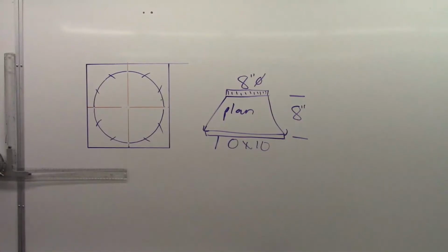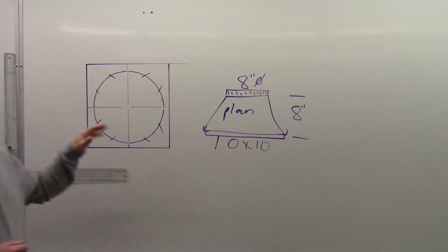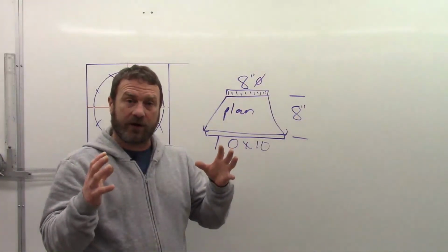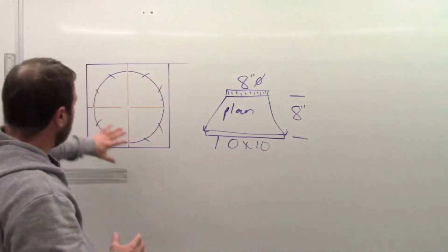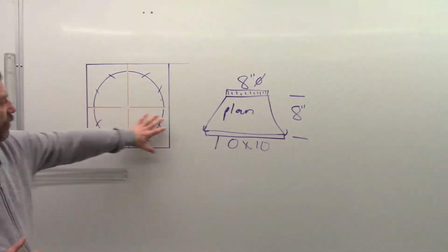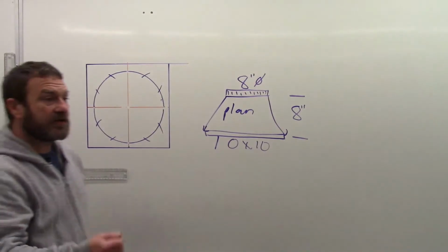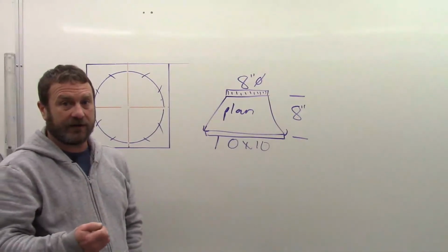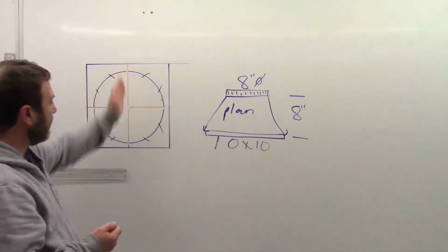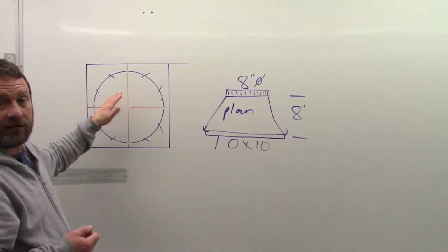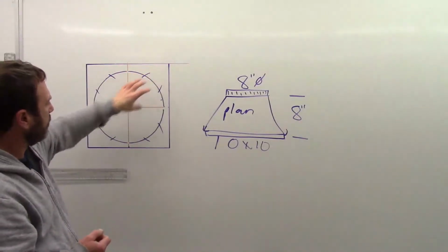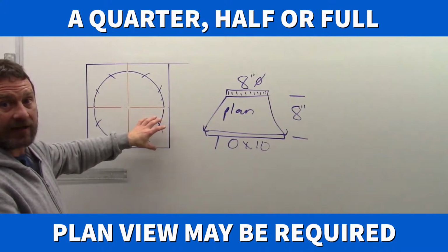A couple of things we can mention when we look at a squared round. A squared round can only ever be formed in halves. We can't actually make or form a squared round in one piece, so we always deal with halves. We're always going to deal with one side of it, and that's it. In most cases, we try to make it so that we have at least one line of symmetry, so that it's symmetrical in one dimension. This one happens to be both ways, symmetrical left and right, symmetrical up and down, so each quarter is exactly the same as the last.